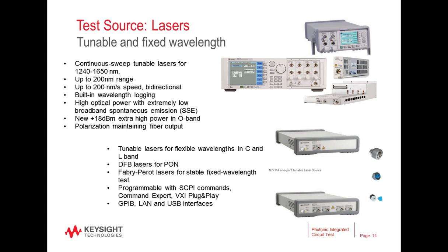Since the laser is a fundamental tool for providing stimulus, it should be noted that there are a variety of lasers available with different capabilities, and I'll discuss that a little bit here. There's continuous sweep lasers that cover a broad wavelength range, and also they can sweep blazingly fast. In some cases, 200 nanometers per second, or that would be 25,000 gigahertz per second. And it can tune over small ranges, like 3 sweeps per second. So it's quasi real time.